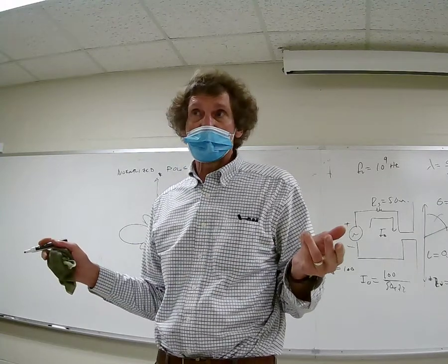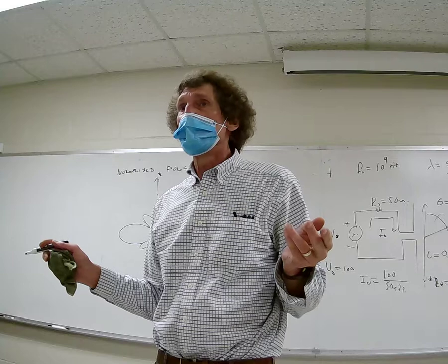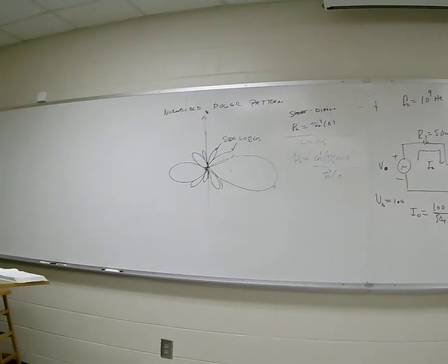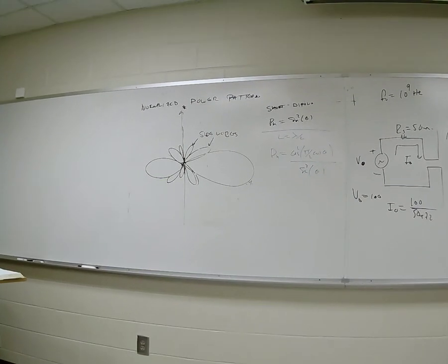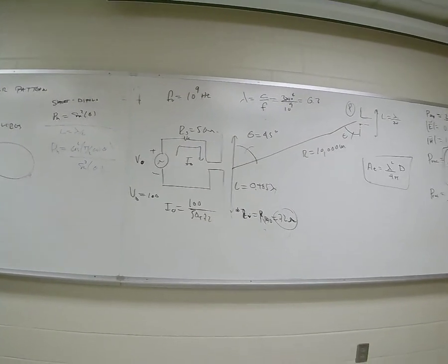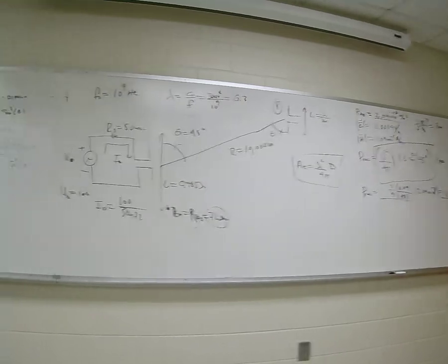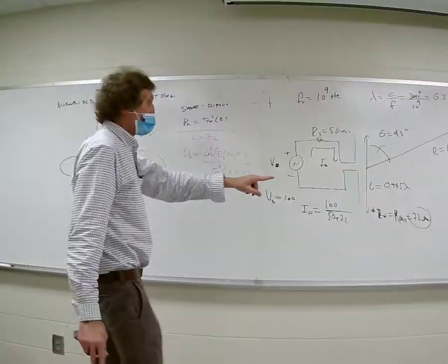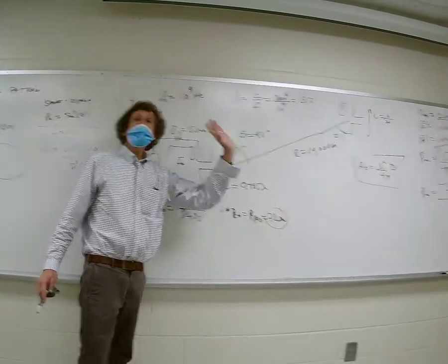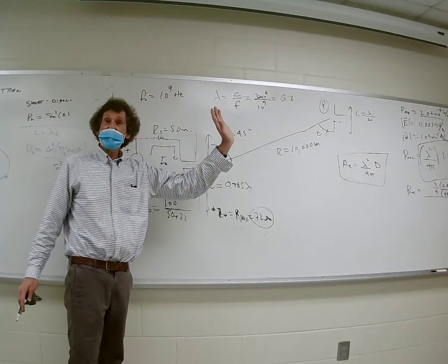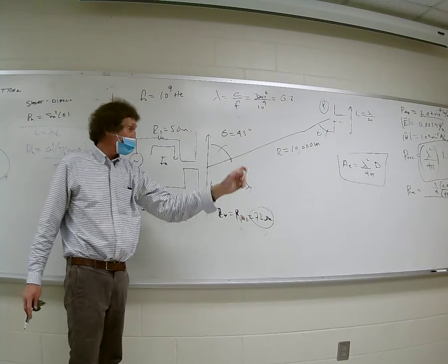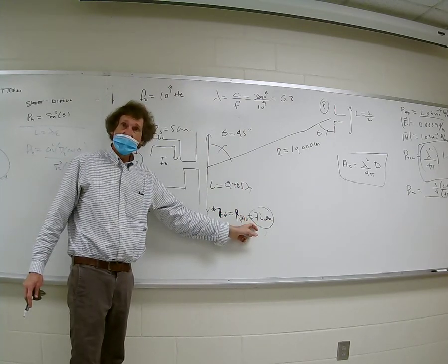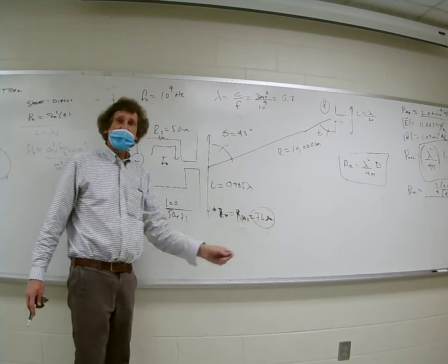The problem we just did was a long dipole, wasn't it? No. That was in the beginning. I said this is the E field. It was a half wave dipole. And then it was a short dipole. Just look, here I said it's 0.485. The reason I did that, the E fields will be the same as if it was a half wavelength in H, but the difference is you only have a real component of resistance, the input impedance. That was the key. And I don't like trying to trick you.